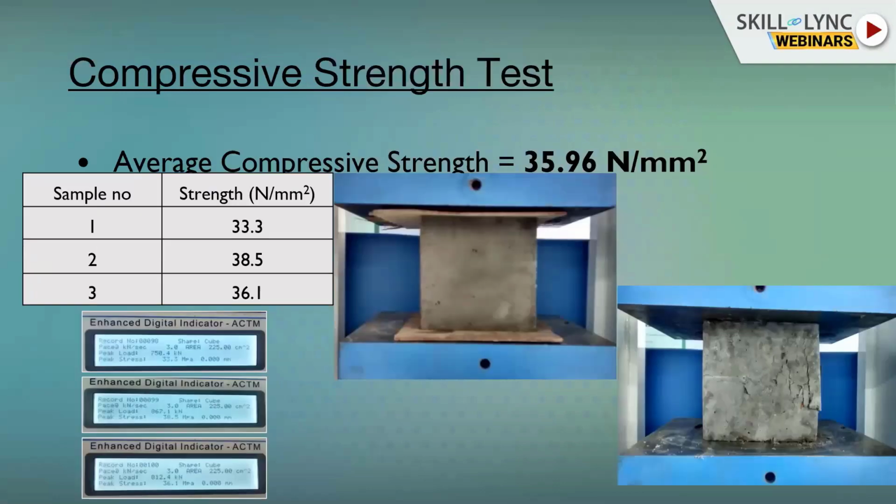So after doing the tests on the materials, the cement, the fine aggregate, the coarse aggregate, and on the concrete, before going to the site, we make the samples. For example, if we design M25 or M30, that means 30 Newton per mm square, or M35, we have to check that sample whether our design is okay or not. We do this on the universal testing machine to check the compressive strength. We put the load on the samples, 150 by 150.